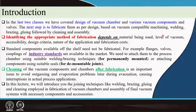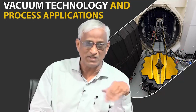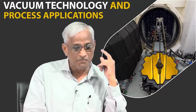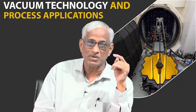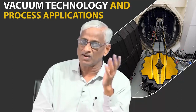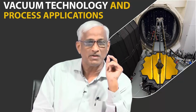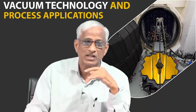So finally, when you are assembling things, what components need to be introduced and which type of technology you have to take, whether it is brazing or something else, it is all decided by the level of vacuum and the purity requirements. Sometimes 10 power -5 torr is required for two applications, but in one place you cannot withstand even parts per million of oxygen, while in the other place 10 power -5 torr is just meant for 10 power -5 torr.